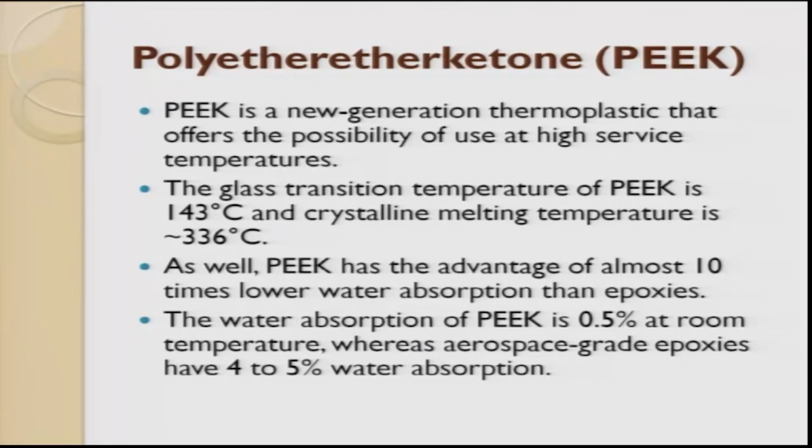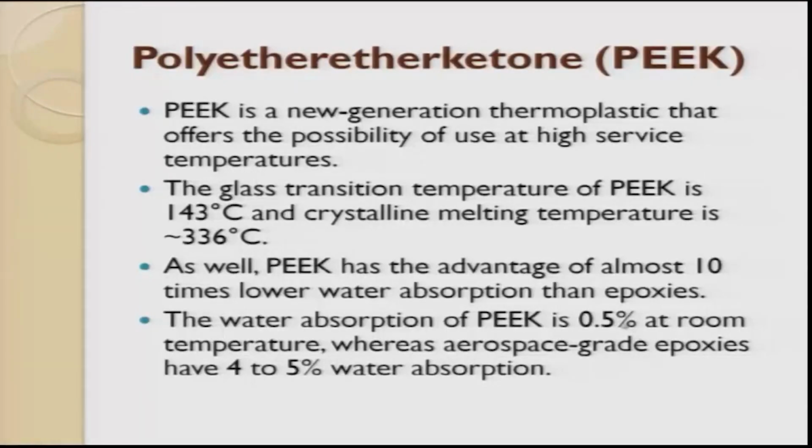What happens if it absorbs water? There is a property called hygroscopic. Water gets absorbed and the polymer gets swollen. This is a very common feature in polymer matrix composites. If at all there is a defect or a crack, and water enters through this crack, it tries to swell the polymer. That kind of defect will not happen with PEEK. The water absorption of PEEK is around 0.5% at room temperature, whereas aerospace grade epoxies have 4 to 5% water absorption. So look at it, the epoxy is a thermoset. Thermoset absorbs and expands, whereas PEEK has an absorption of 0.5%.